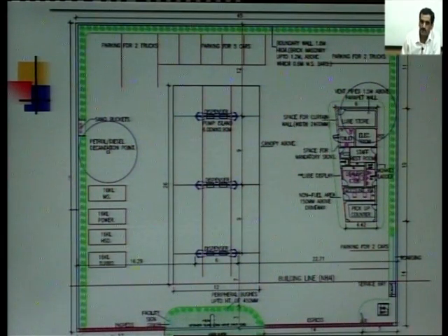So these are the norms as per your national highway, but these norms are not followed in the city outlets, where the ingress and egress depends, and starts from 9 meters to 16 meters. On a highway it's around 12 meters to 40 meters, and in a city it's around 9 meters to 12 meters.